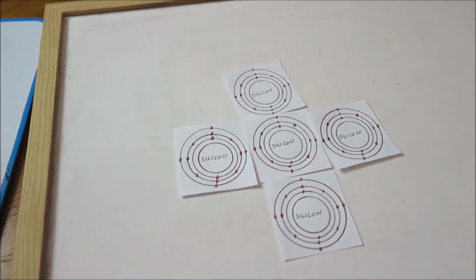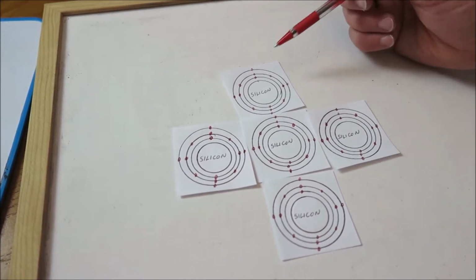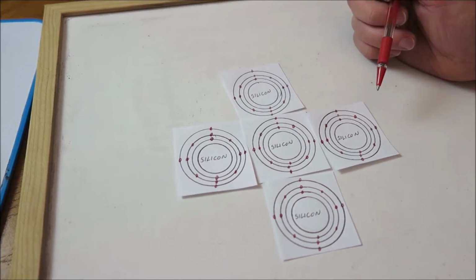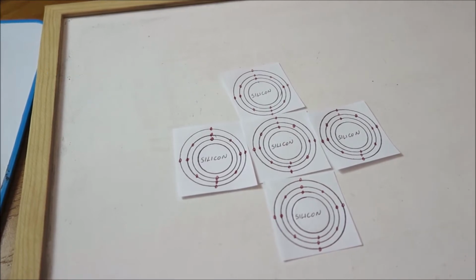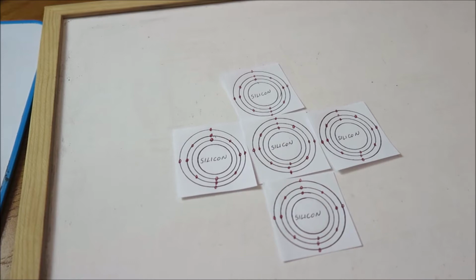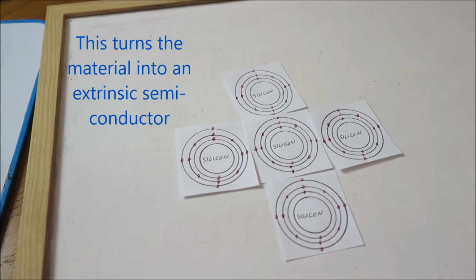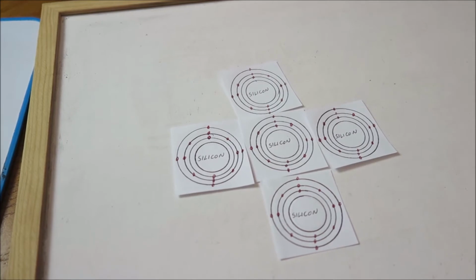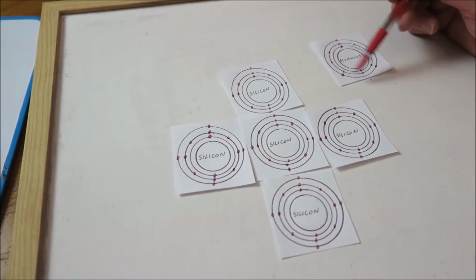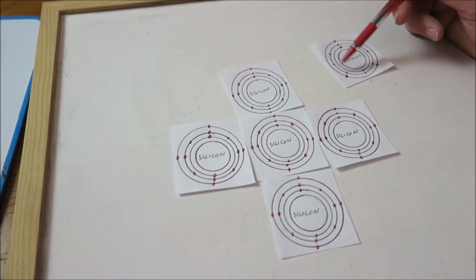Now, silicon is a poor conductor at room temperatures, but there's enough energy to allow some free electrons and some electron movement, so you can get a tiny current through it. But we want more than that. So what we need to do is to add other materials to the silicon. Now this process is called doping, and that's an important one to remember. Doping means you add other atoms to it, and you can have aluminium, which is a trivalent material. There are a number of different trivalent materials, one of them being aluminium, so you can add aluminium to it.